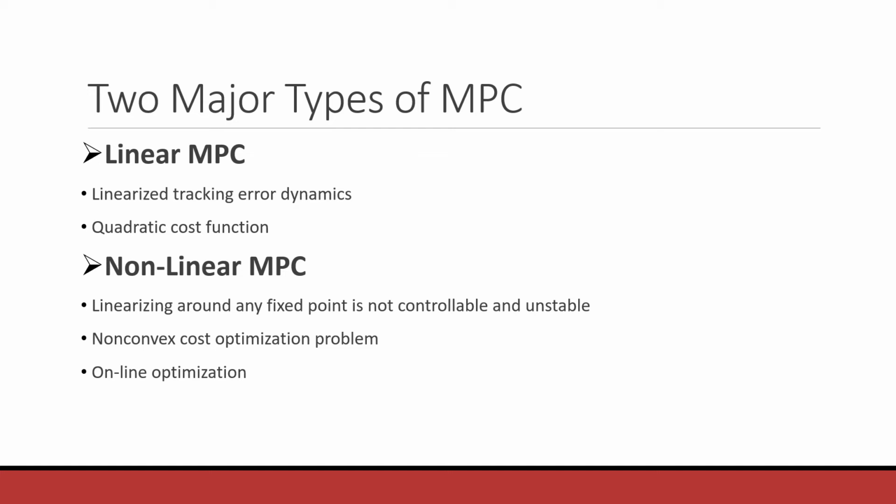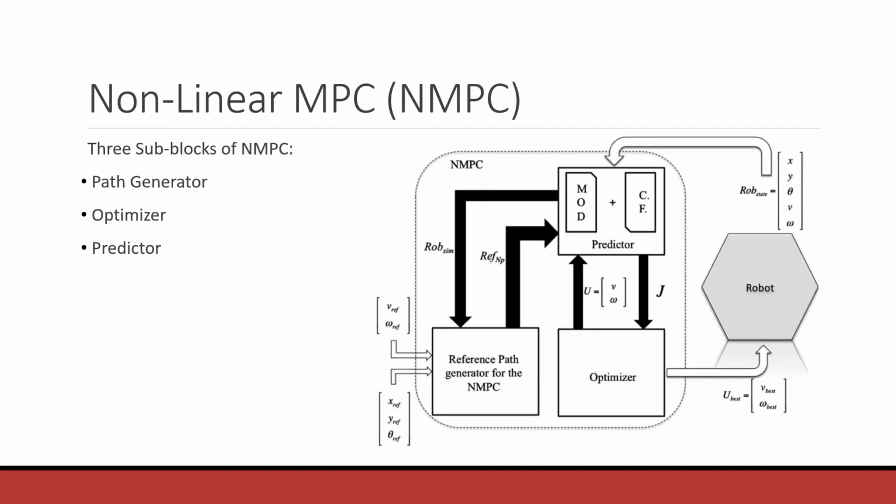Now, non-linear MPC. Since linear MPC is not feasible for the mechanical benchmark problem, the potential of non-linear MPC techniques has been investigated over the years. Nonlinear MPC implementation demonstrates that the cost and reliability of non-convex optimization are critical issues, making the tuning of controller parameters decisive. In general, terminal state constraints are required to guarantee asymptotic stability. Let's focus on the nonlinear MPC model in detail.